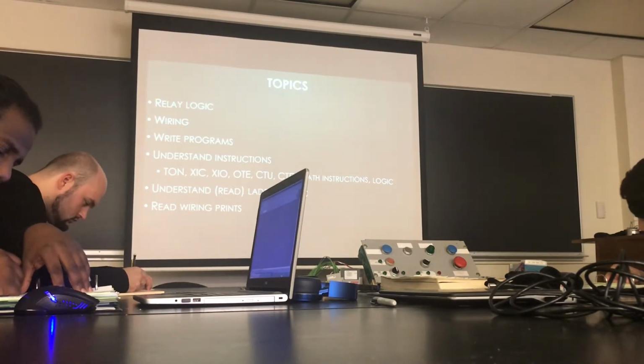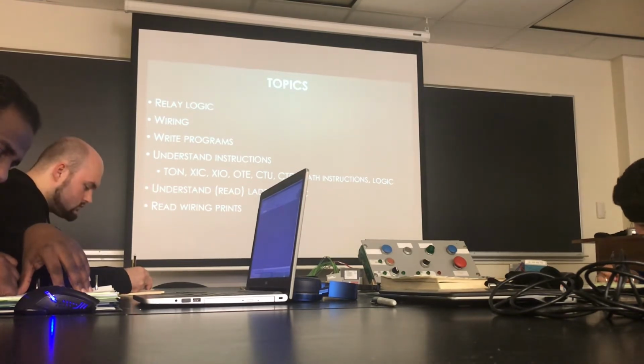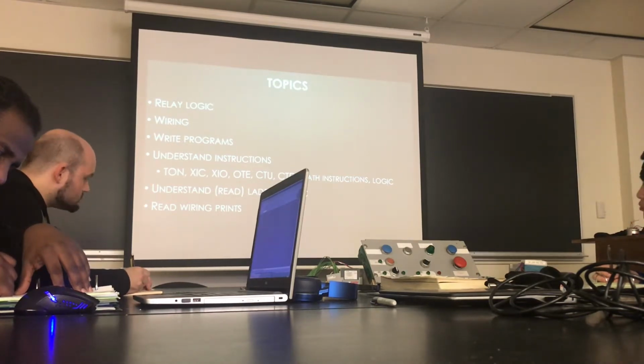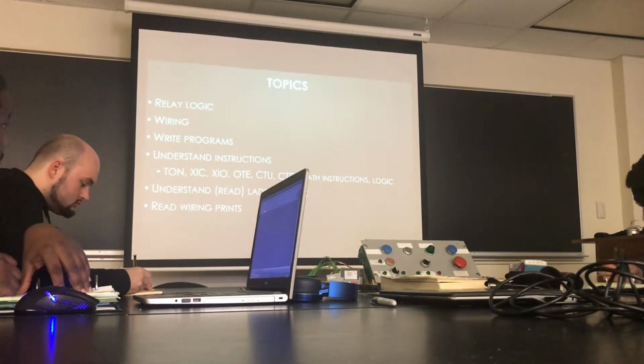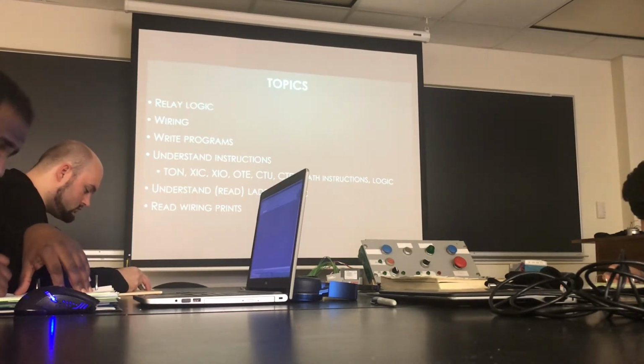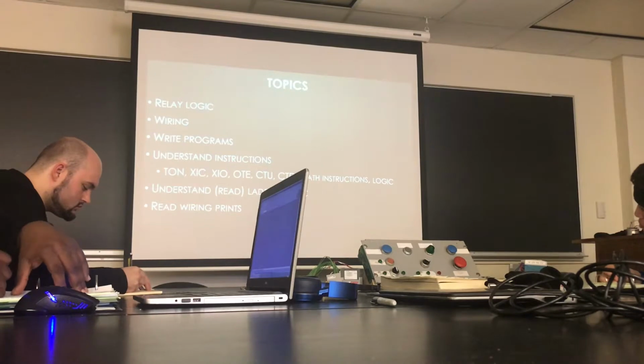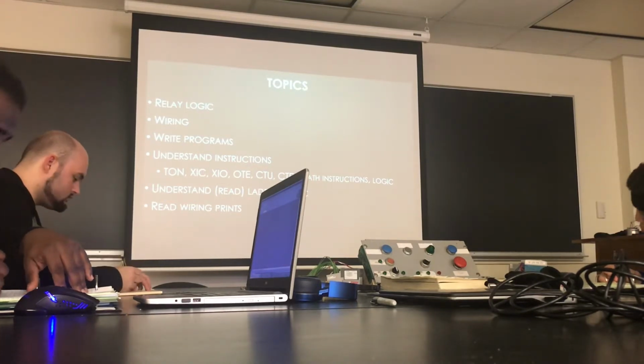So the TT, the EN, and the DN. Are there any bits associated with an XIC command? No. Right? Count up or count down. Counter done. About it.